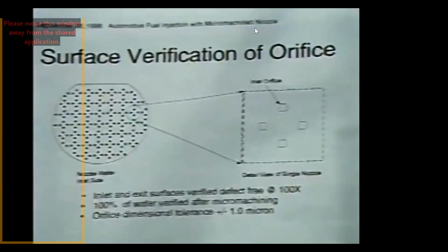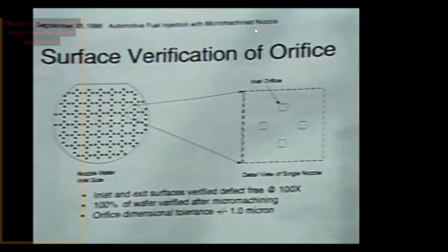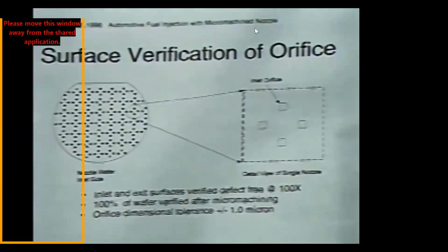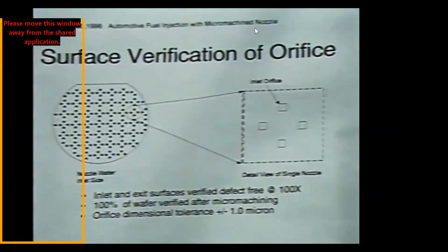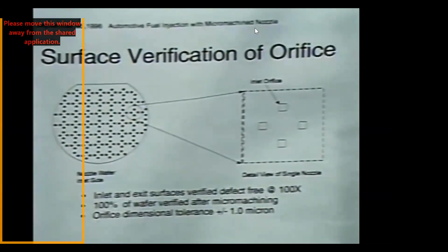We had a very high magnification inspection system, and we would inspect the size of each orifice. These sizes were then converted into a dimension that we would graph regularly and control on our system. If something was too large or too small, it would be put onto a wafer map and later rejected in our pick and place operation.